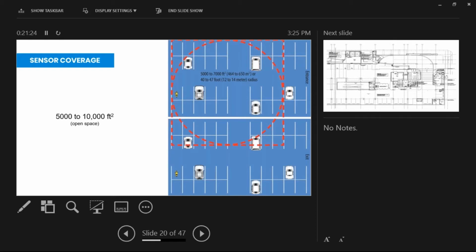So you're going to want to space your sensors out throughout those aisleways and the open area of the receiving shipping area of the warehouse, such that you can provide adequate coverage, and your sensors are no more than 80 to 90 feet apart.